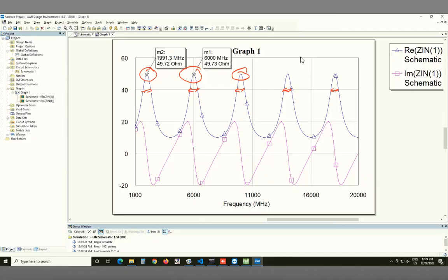Right? So this again is something which happens a lot in these kinds of structures. The higher the frequency you go, for the same fractional bandwidth, you will get more absolute bandwidth. Here it's the opposite effect. It's the same absolute bandwidth, but you're going to higher frequencies, so the fractional bandwidth is getting smaller. So the correct statement about what a lambda by 4 versus a 5 lambda by 4 or 3 lambda by 4 transformer is, in terms of bandwidth, is that it changes the fractional bandwidth. It will reduce it. But for a single section of line, that response is exactly the same as you go from one to the other.